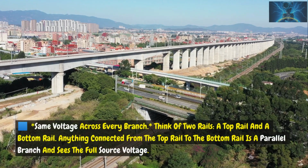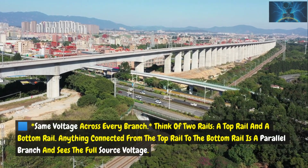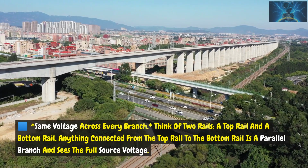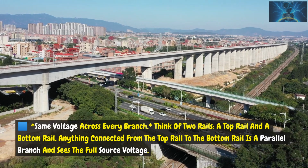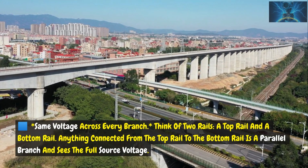Same voltage across every branch. Think of two rails, a top rail and a bottom rail. Anything connected from the top rail to the bottom rail is a parallel branch and sees the full source voltage.